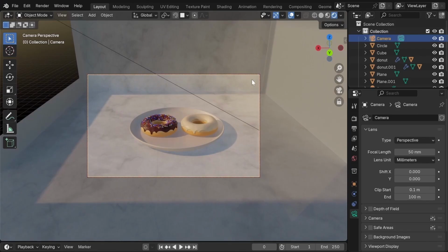Alright, at this stage the skylight is working well, but the lighting is still slightly uncontrolled. If you look carefully, the back wall is bouncing too much light back into the scene. This reduces contrast and flattens the image. In photography, artists often solve this using a black fill card. A black card absorbs light instead of reflecting it, which helps shape shadows and increase contrast. We're going to simulate that same idea here.